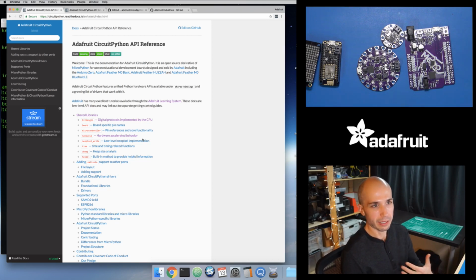support is slightly different in how you do things like access digital I/O or talk to your SPI or I2C peripherals. So just using that same name might make things even worse, because now the import statement would work, but then later on when you try and use your device, things will start failing. So it's a little bit better to just fail early and hopefully catch the error and realize, oh yeah, I'm not using the right code for this board.